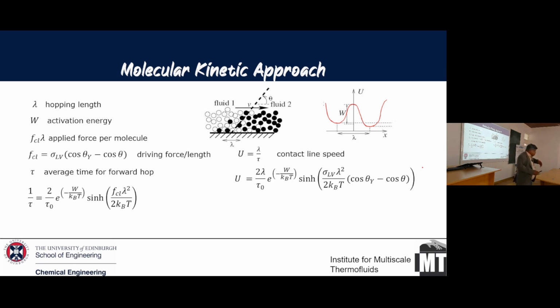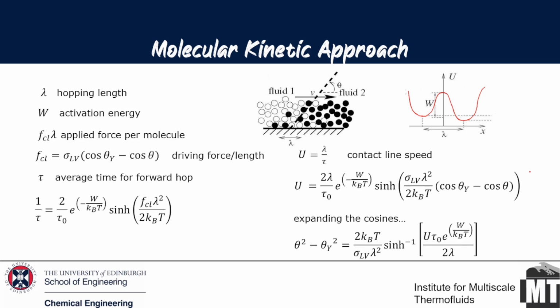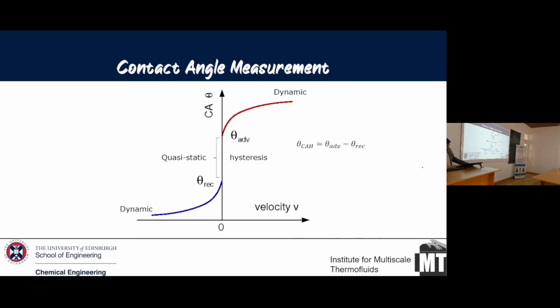So if you have a rapid motion of a contact line, so for example, when you have boiling, you can have almost an explosive time scale, you have a motion there. Those things are not valid here. Okay, so this is from a very slow molecular kinetic approach that you would get some sort of a contact line speed. But of course, not everyone can deal with the molecular kinetic approach. Okay, you need to have continuum physics. You want to develop your surfaces and all that. You need to have that. So this is just an explanation about what the molecular kinetic approach is.